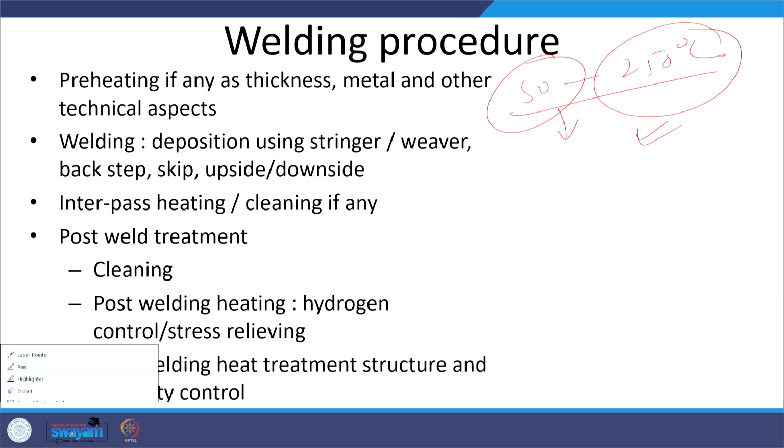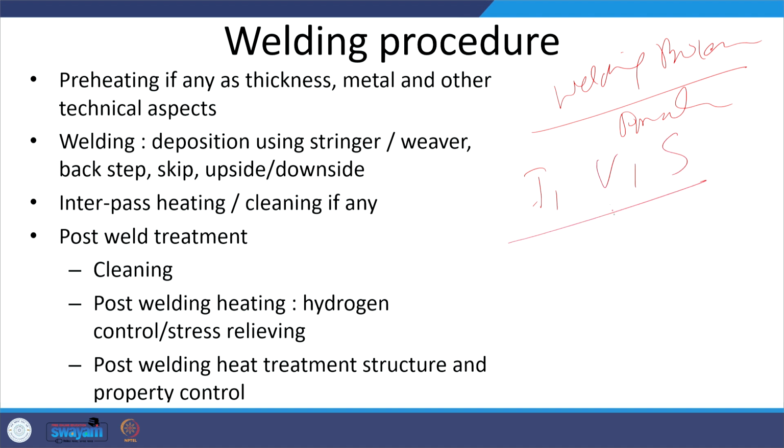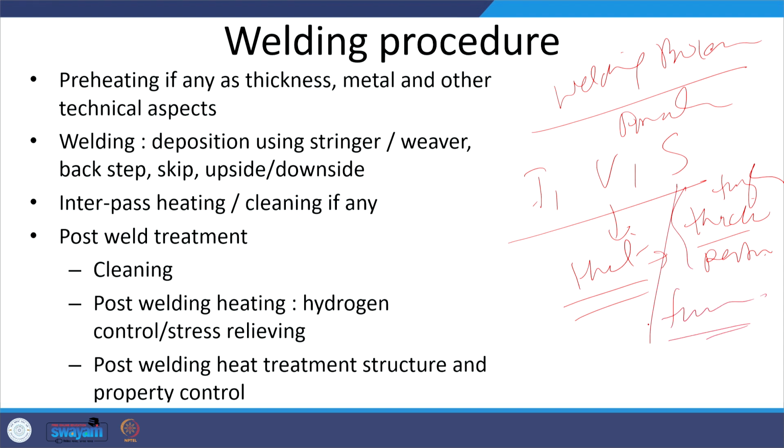Now, when the welding is done, say we have chosen a suitable weld for a given welding process, and we have selected suitable welding process parameters. So, what are those? We have selected current, voltage and welding speed such that we get the desired net heat input, to realize either through-thickness penetration, or the desired fusion of the base metal surface. Once this heat input is realized, then metal will be deposited.